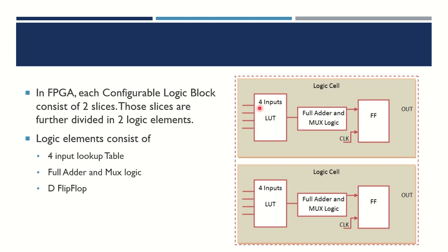Let's consider these as F, G, and H. The function block can get its inputs from the F and G lookup tables and from any external inputs. The function generators are programmed to generate three different functions of three independent sets of variables, an arbitrary function of five variables, and an arbitrary function of four variables together with some functions of six variables. Some functions might even involve around nine variables.